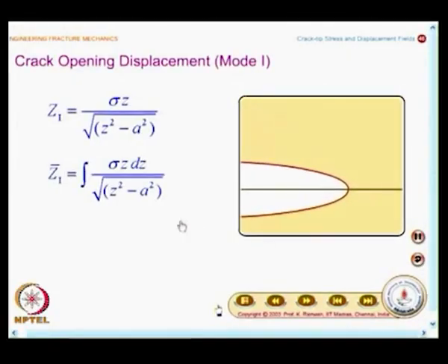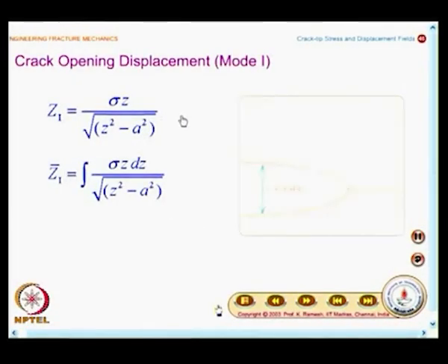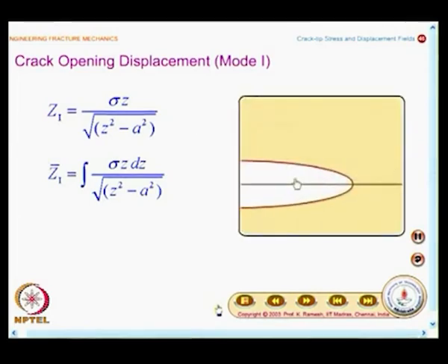See, one of the things that I have been mentioning in earlier classes was, when the crack opens, it opens like an ellipse. When I make a statement like this, once you have got the displacement field, you will also have to evaluate it and reconvince ourselves, yes, the crack opens indeed like an ellipse.